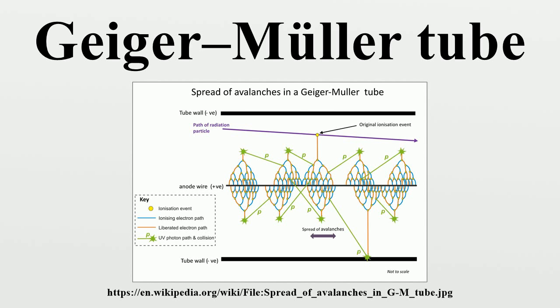The strong electric field created by the tube's electrodes accelerates the positive ions towards the cathode and the electrons towards the anode. Close to the anode, in the avalanche region, the electrons gain sufficient energy to ionize additional gas molecules and create a large number of electron avalanches, which spread along the anode and effectively throughout the avalanche region. This is the gas multiplication effect, which gives the tube its key characteristic of being able to produce a significant output pulse from a single ionizing event.